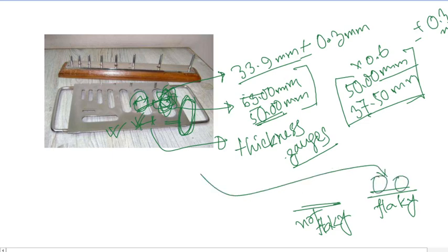So all the flaky particles, each tested against its specific opening, are kept together as flaky particles as a whole, and if a particle does not pass, keep it in another pile as not flaky.